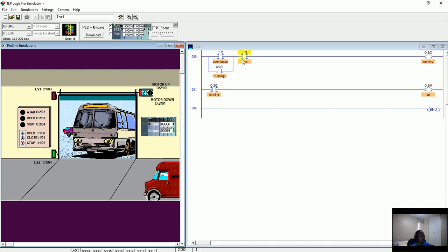stop. So otherwise, in order for the door to auto stop, we need to introduce this limit. So this limit, you just need to look at the striker. You can see that the striker is adjusted in the downwards position, and if this door is going up, it's going to make the striker while it's going up.